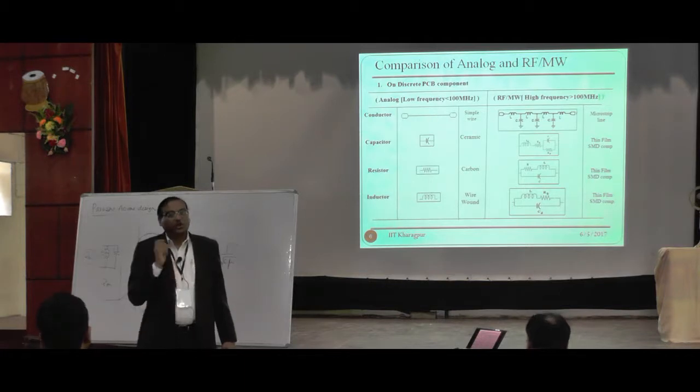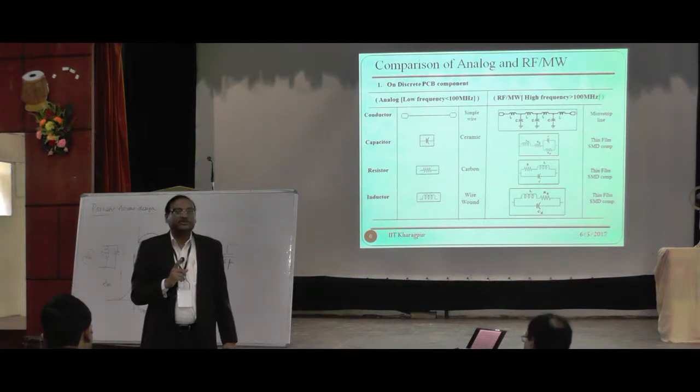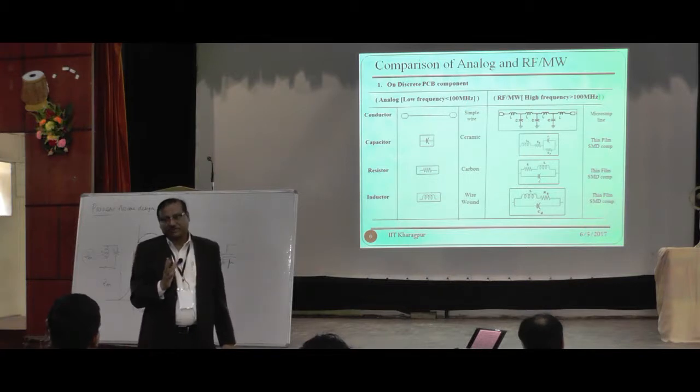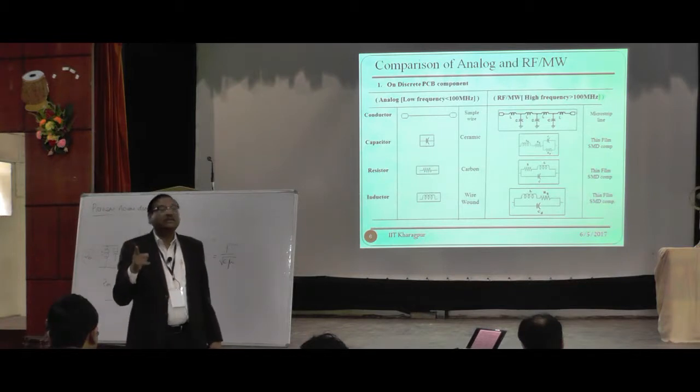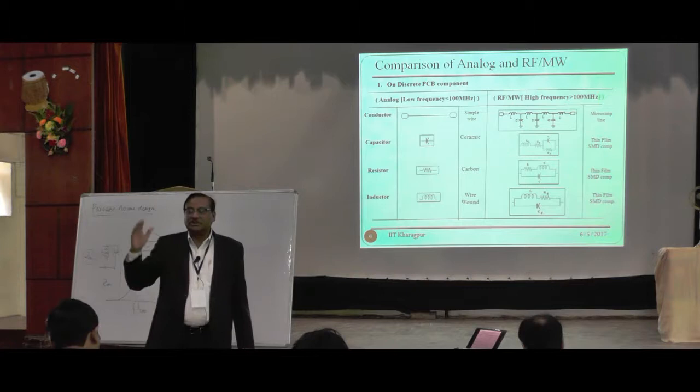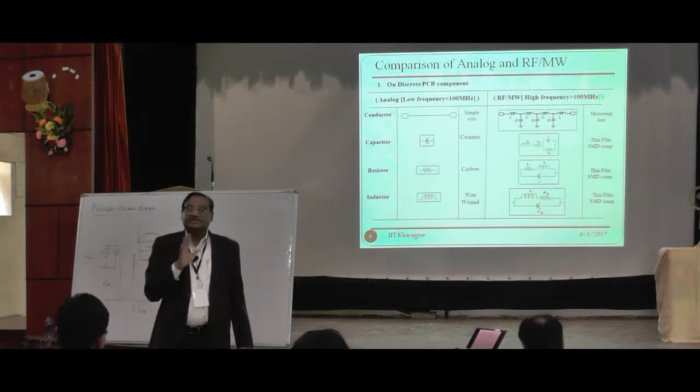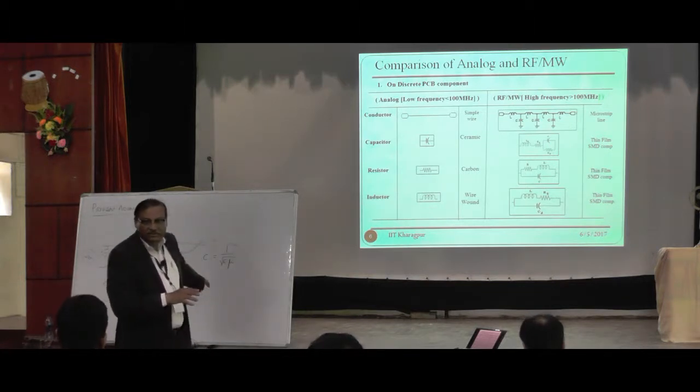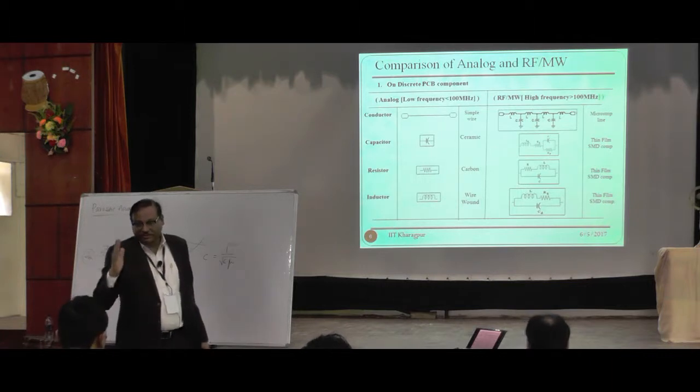Second, all the components which you are trying to incorporate in your design, its self-resonant frequency should be as high as possible compared to the operating frequency. Then you cannot design. Okay? So those things are pretty important. You have to find out what is the, in case of transistor, what I said, the cutoff frequency. Cutoff frequency means the frequency of unity gain band. And the self-resonant frequency, just as explained. So those frequencies are the limiting factors.